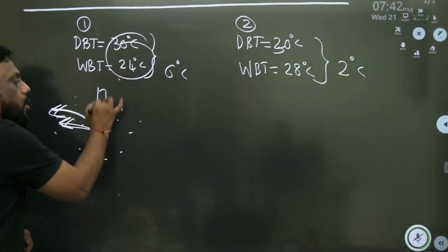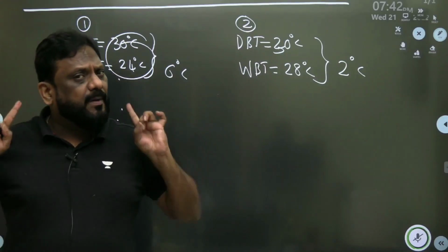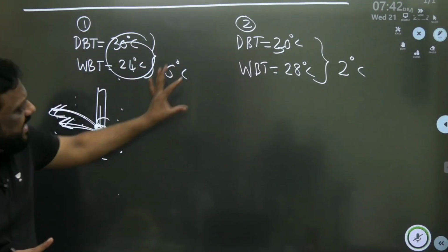That's why you are feeling more drop. So please observe, we are not actually interested in the wet bulb temperature. We are actually interested in the difference between dry bulb and wet bulb temperature. Here the difference is less.